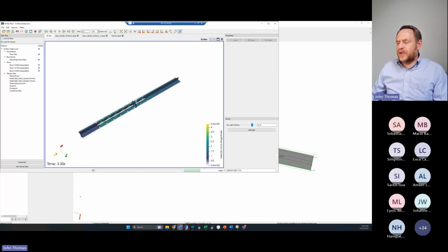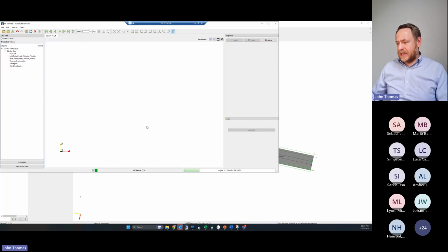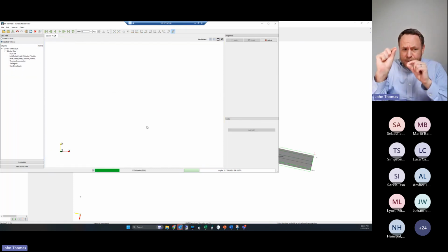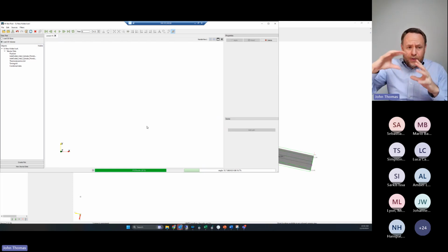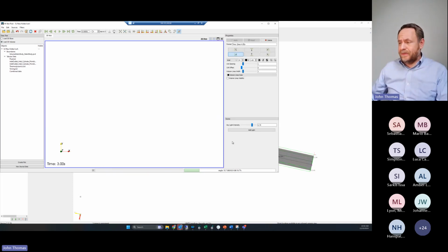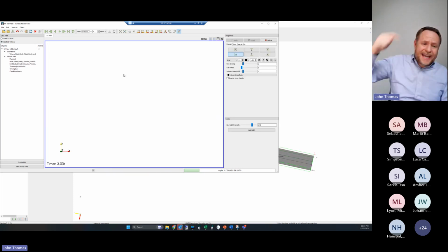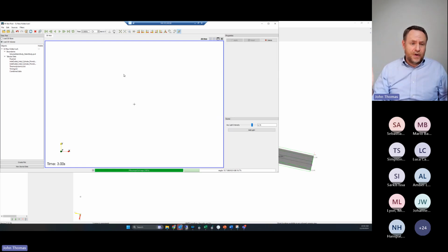Let me go back over to this. I'll show it here again. So here's my 3D representation. I can calculate the energy dissipation rate at every point, as it were. I can integrate that energy dissipation over the entire system. I can sum it up, and I can check it against the pressure drop times the flow rate and see that they're within like 4%. That's a pretty cool application of both energy conservation, the first law, and the LES filter.